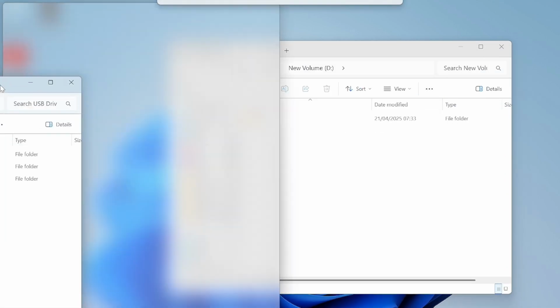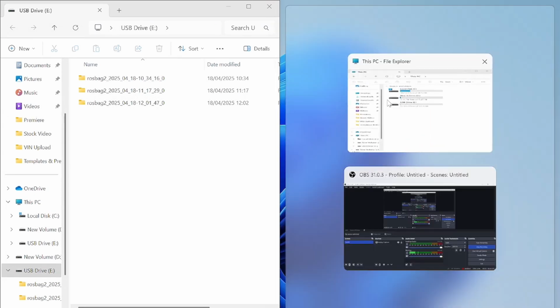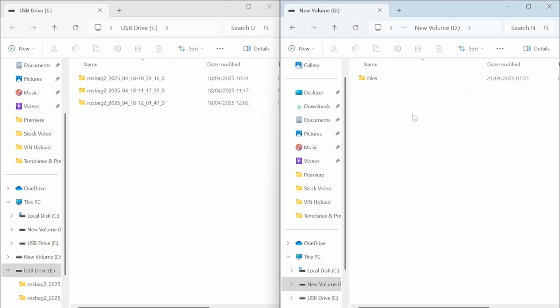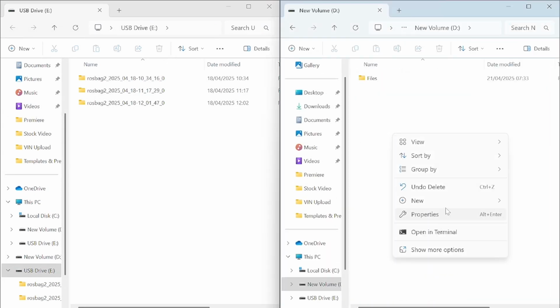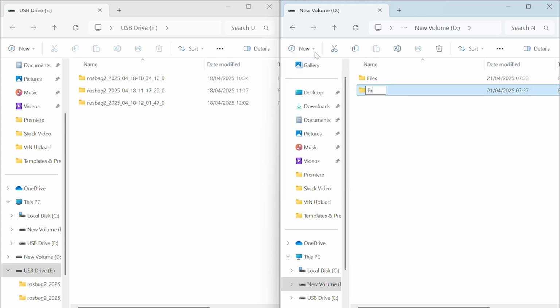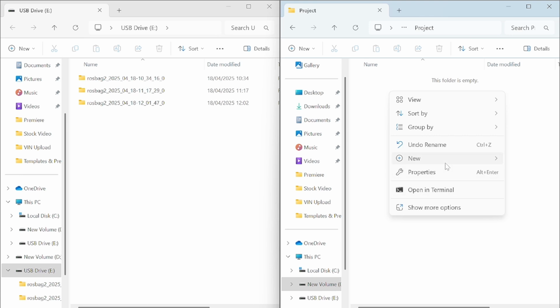Copy USB ROS files. Make sure to add them to the right blade when sorting them, using order or timestamp to identify it. Create a folder on the hard drive named with the project code. Inside it, create subfolders for each wind turbine inspected. Use clear naming, such as the turbine's ID and inspection date, for easy reference.